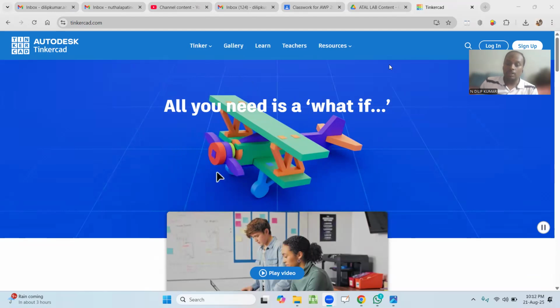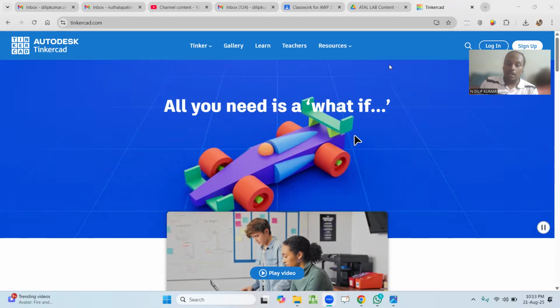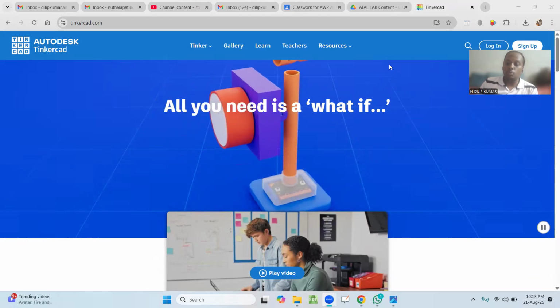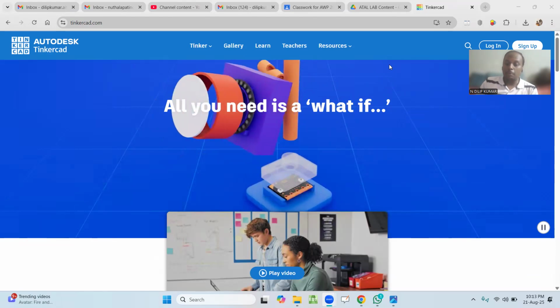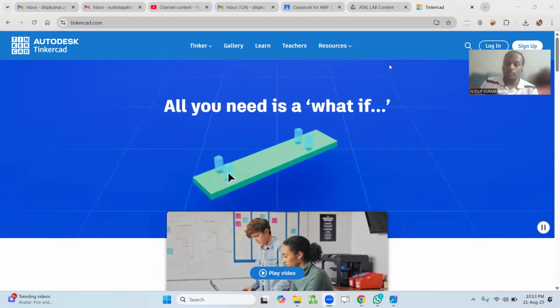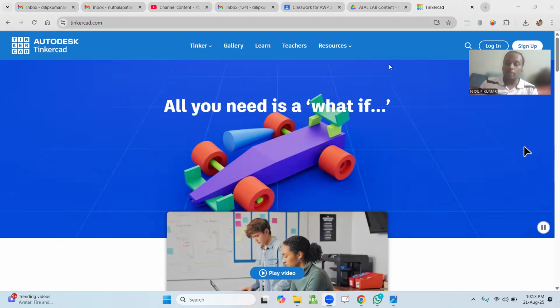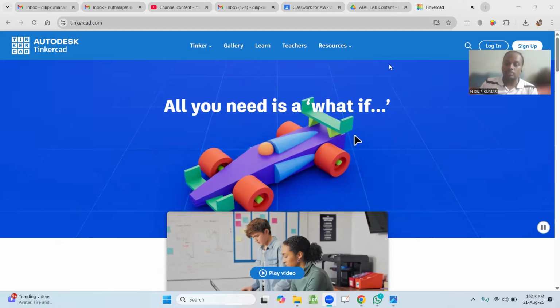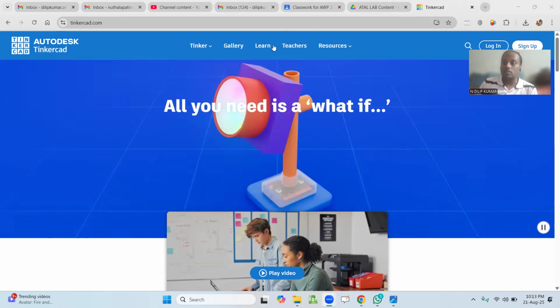Whereas in a parallel circuit, all the components are connected across the same 2 points, side by side, so there are multiple paths for the current to flow. Here the current is divided into the respective paths, the voltages are the same, and the current divides across the respective branches depending on the resistance in each parallel branch.